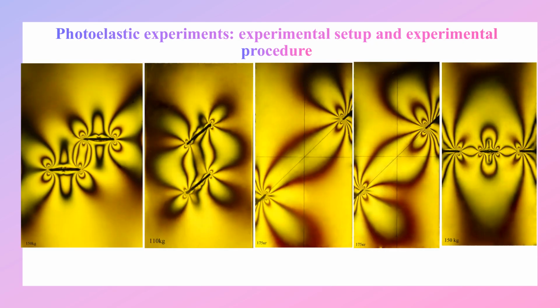Actually, we consider different crack geometries. Thus, you can see isochromatic maps for different cracked geometries. Here you can see the specimen with two parallel cracks, with two inclined cracks, with two edge notches of equal and different lengths, and the plate with one central crack and two notches.